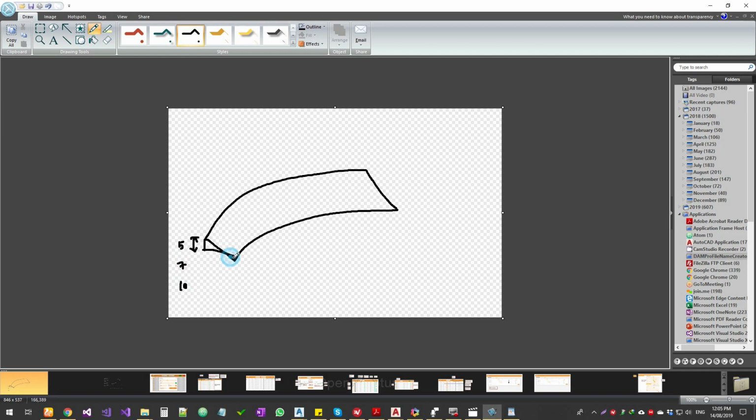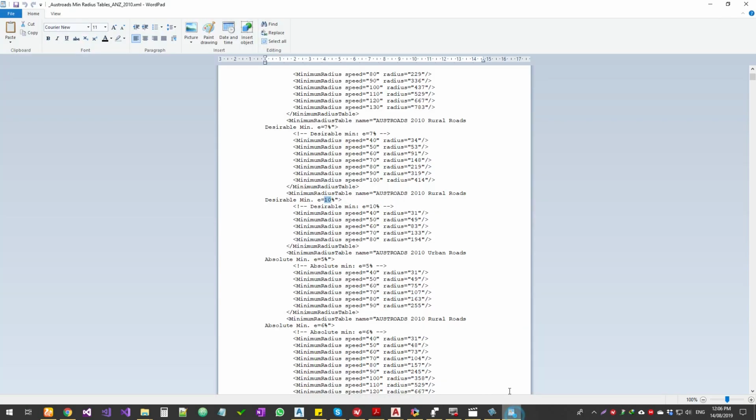In most cases on urban roads, people tend to avoid bigger superelevations because there will be a lot more pedestrians and push bikers, and a lot of these people will not be traveling at the minimum speed they need to travel at on the outer edge of the super, which might create some issues. Now going back to the calculation, if you go to a higher super and you're traveling at 40 kilometers an hour, the radius can be shorter.